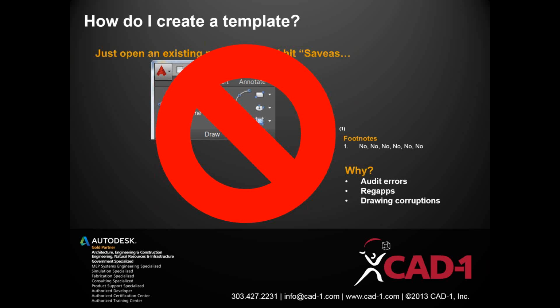And there are, like I said, a lot of types of corruptions that you can import into a new drawing this way. There are audit errors, and that's database errors inside your drawing. There are things called reg apps. We've been finding all kinds of problems with reg apps corrupting drawings. There are drawing entity corruptions where an object inside your drawing gets corrupt. So there's all manner of corruptions that can occur to a drawing.